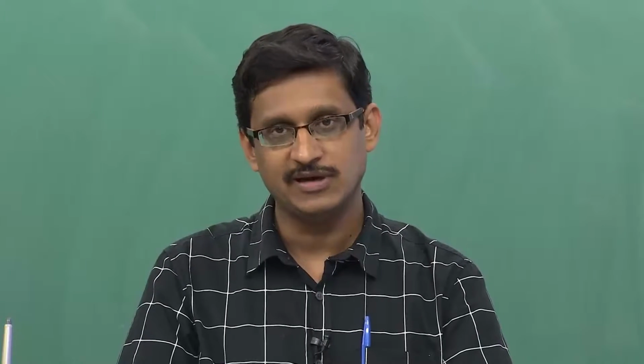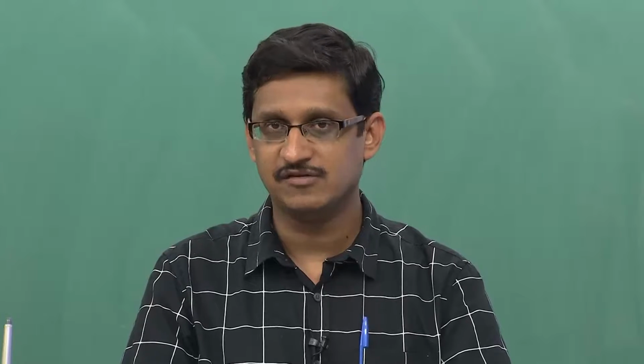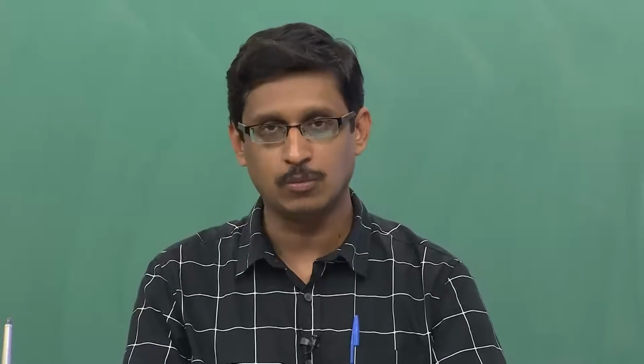In this module we will discuss the power spectral density of the pulse shapes, which is a continuation of the previous module where we had discussed the type of pulses that are normally used, especially when you talk about baseband communications. Of course, we are not going to really do baseband communication here with fiber optics, but it is necessary to know what pulse shape we would have, because it would have an impact on the bandwidth and hence the performance of the system.